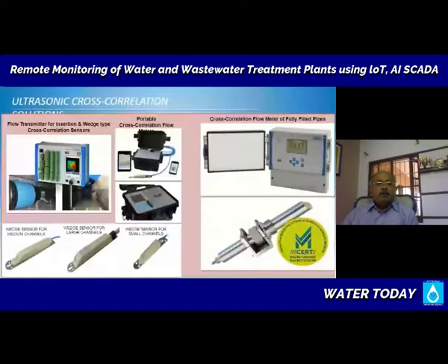Now, for the sensors that are available, you will see the sensors in a sleeping arrangement, like a wedge. The wedge has got two sensors. You will see a couple of dots on the sensor. The one at the bottom is depth sensor. How much water is there? It will send an ultrasound signal from bottom to top. And then it will measure the velocity as well that is flowing in the pipeline and calculate the volume flow.